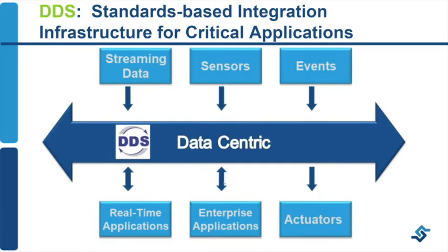So DDS is a middleware that allows you to connect anything. But basically, in this case, we are talking about sensors and actuators. You can consider a robot as a set of sensors and actuators. And you can think in a distributed robot. It's not only the typical wired robot with sensors and actuators, but imagine that you have also IoT components in a room and the robot. You can consider the whole set a distributed robot.